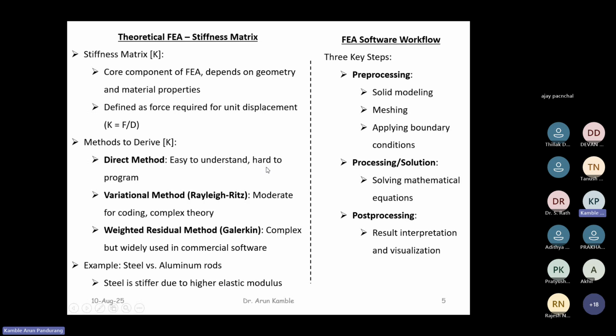In this, there are three steps: pre-processing, solution phase, and post-processing. In the pre-processing phase, we do the solid modeling, then the meshing, and we apply the boundary conditions. In the solution phase, we solve the mathematical equations, and then in the post-processing, we interpret the results.